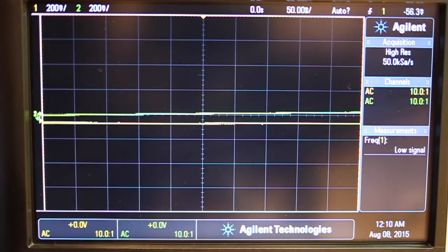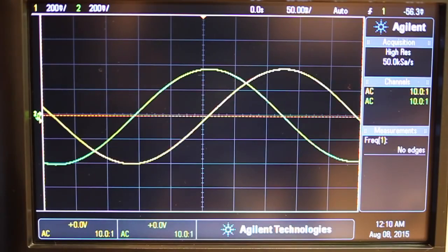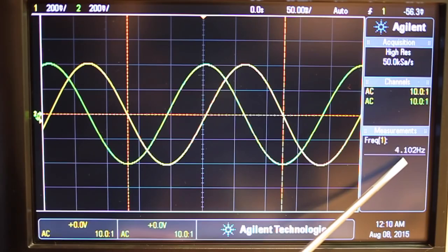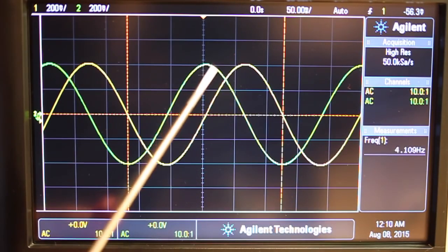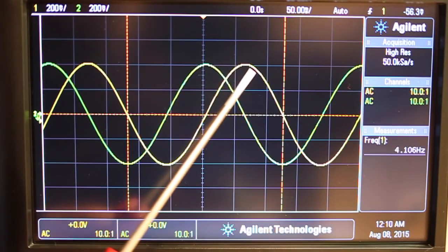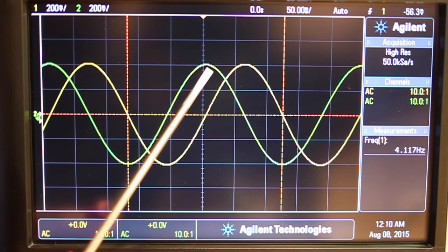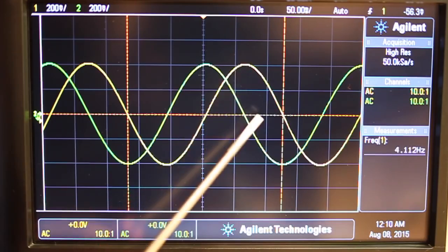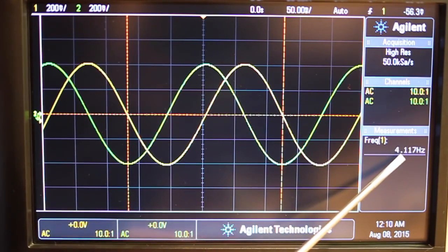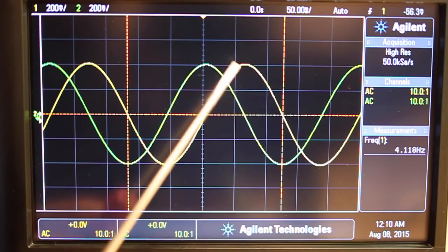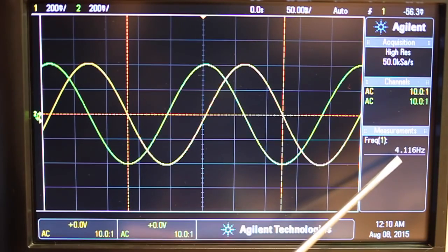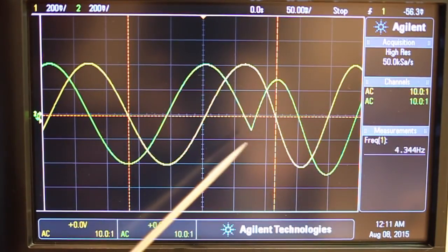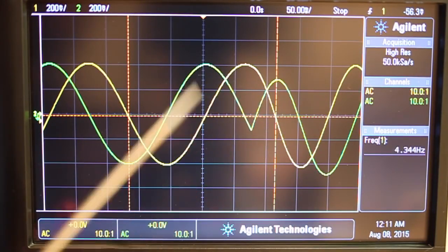But as I come up on the other side here, I'm now 4 Hertz away from my local oscillator, but we can see there's been a change in this phase relationship between I and Q. The Q signal is now leading the I signal. So we can tell that I'm now 4 Hertz below the local oscillator, whereas before I was 6 Hertz above. And we can see that transition very clearly here.